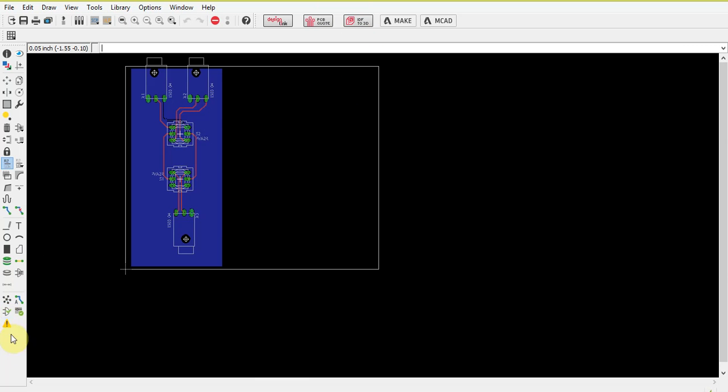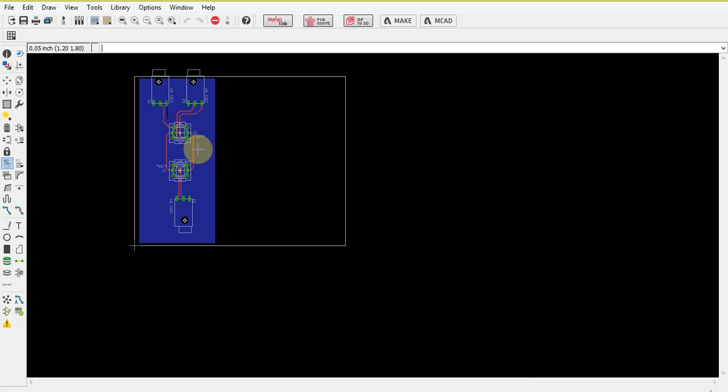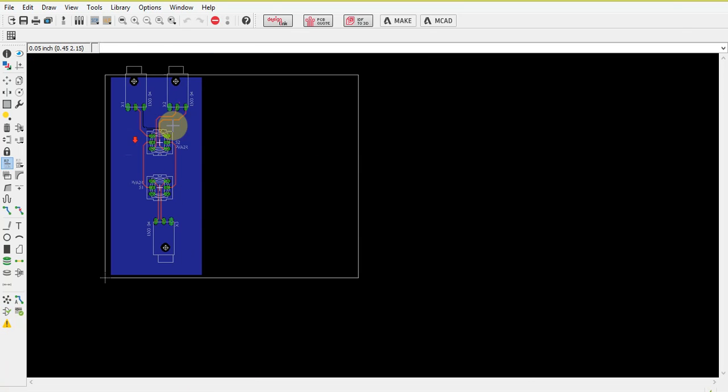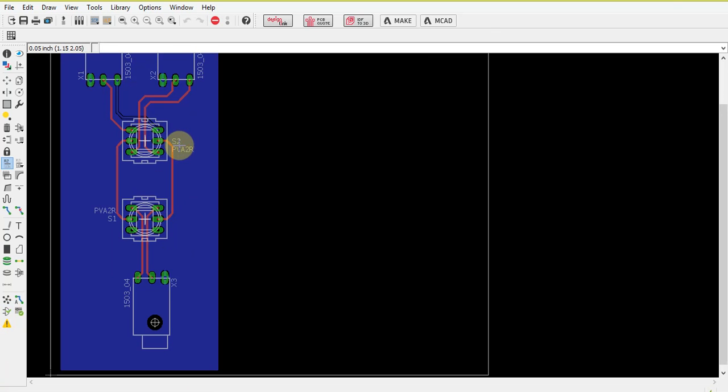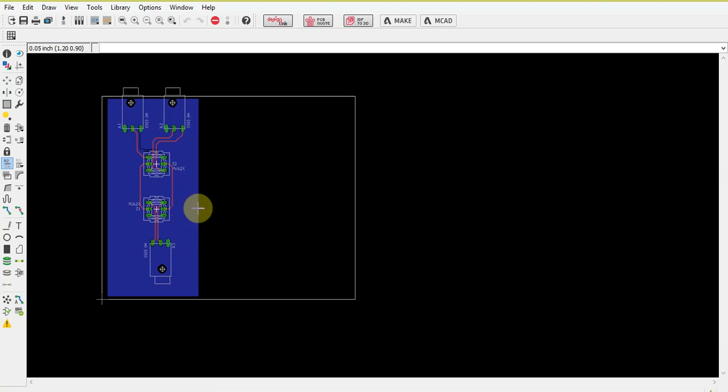So to see if the schematic and board are consistent. If there are unconnected traces here and there, that will show up as an electrical rule violation, meaning you have something laid out in the schematic, but they don't correspond on the actual board layout. So then you'll have to fix that by disconnecting and so on.